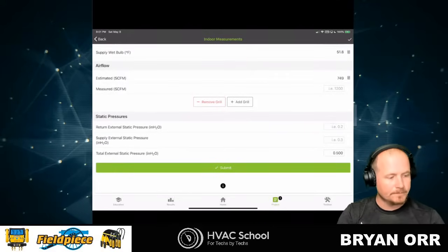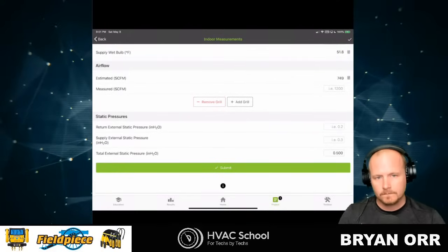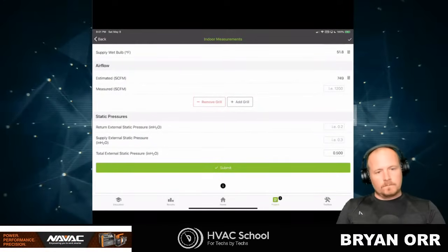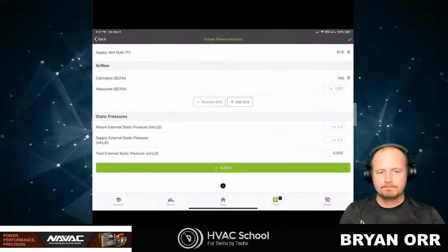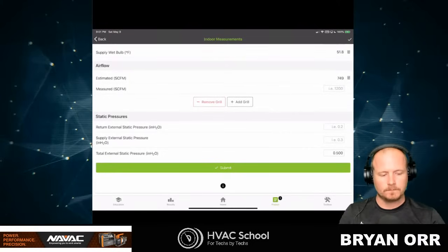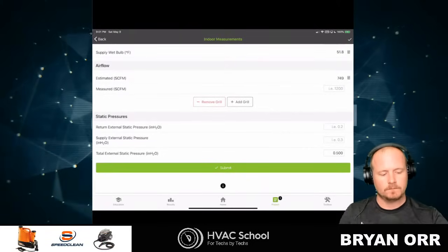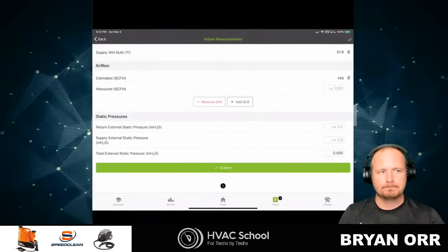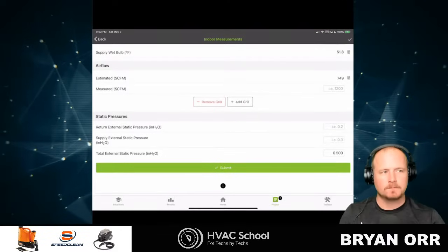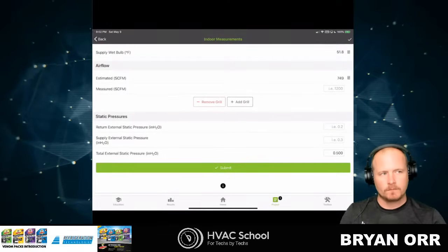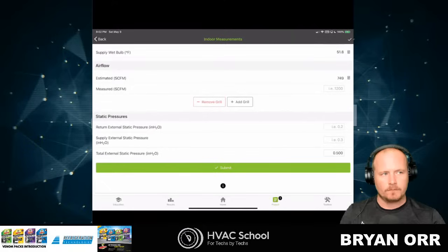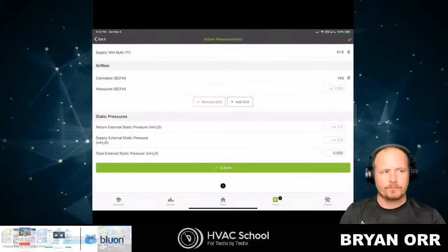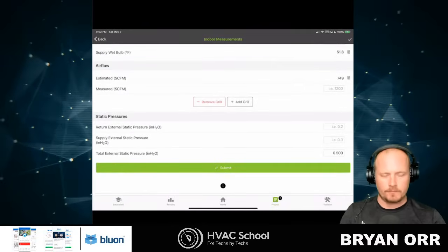Yeah, and another note on that: if you use another measurement method of measuring airflow, a lot of guys say your measurement's too low or too high. Most of the time people say it's measuring too low. Well, what usually happens is they have poor probe placement. It's too close to the evaporator, and it's seeing line of sight of the evaporator coil. So when they put in their airflow, if it's a 5-ton system, it might be doing close to 5.5 to 6 tons of cooling, because they're getting this ridiculously high change in enthalpy because the probe placement's poor.